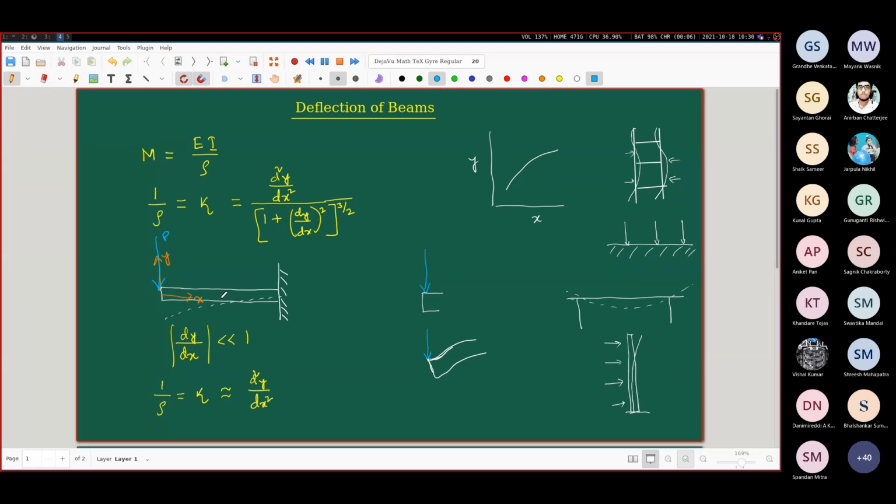So we never actually say that we are going to write the deflection strictly at x equal to 0. But of course, for approximate purposes, we write like that, with the understanding that we are actually slightly away from the actual application of the load point. Okay, and this particular principle, where we always stay away from the actual application of the load points, is referred to as the Saint-Venant principle. Okay, so remember this, the Saint-Venant's principle.